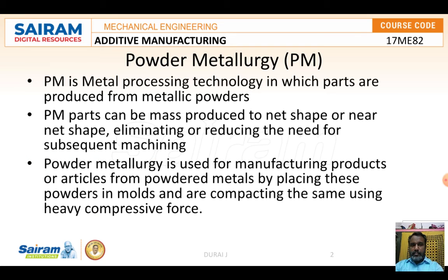First we are going to discuss powder metallurgy. Powder metallurgy can be defined as the science of producing metal powders and making semi-finished and finished objects from individual, mixed or alloy powders, with the addition of non-metallic constituents. So it is possible with addition, or otherwise without addition also.